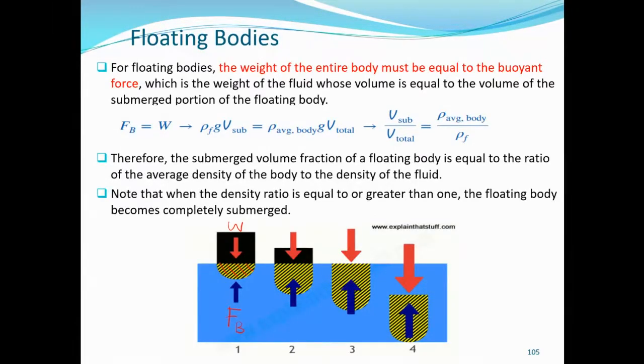Now, for the weight of the body, when you take equilibrium, this is the free body diagram. If you apply equilibrium here, the sum of forces in the vertical direction is equal to 0. So you will realize that the buoyant force FB is equal to W, the total weight, not the submerged weight, of that object. This is analogous to, let's say, your palm.